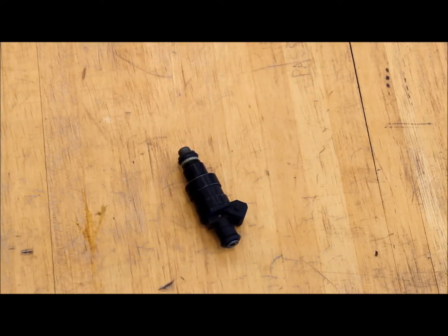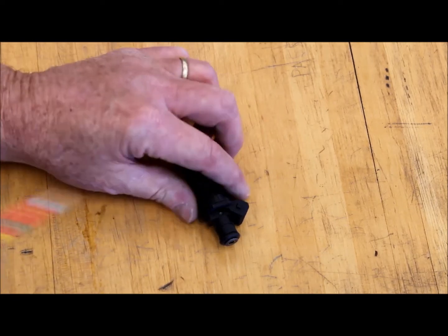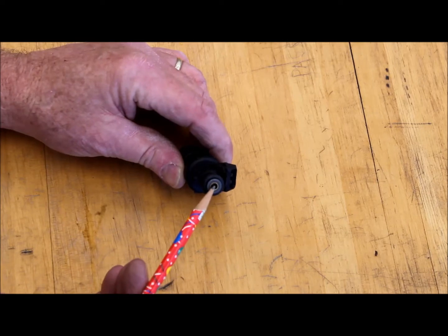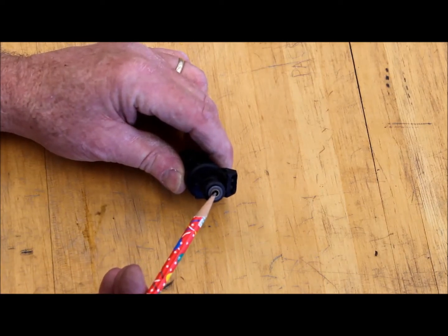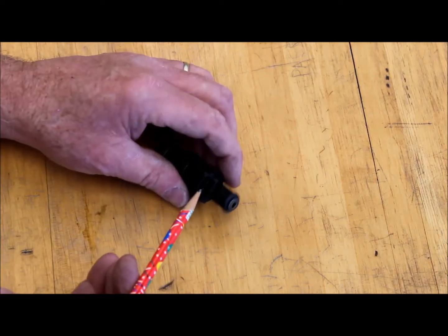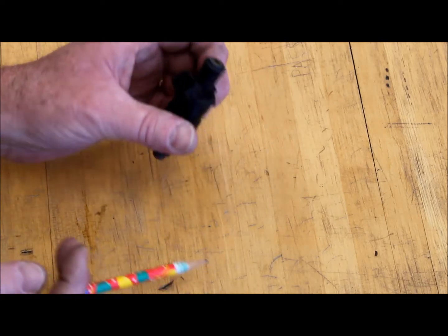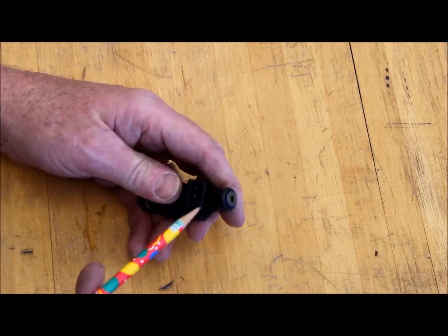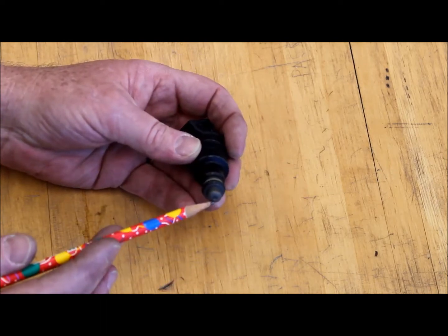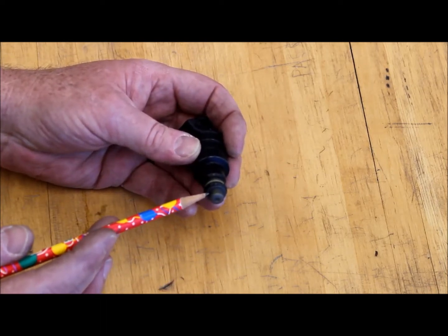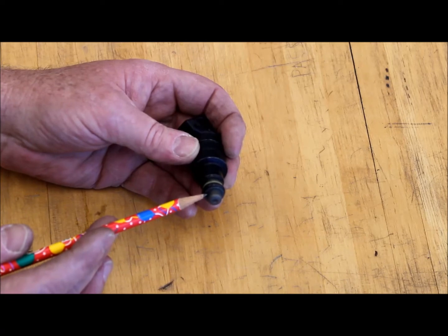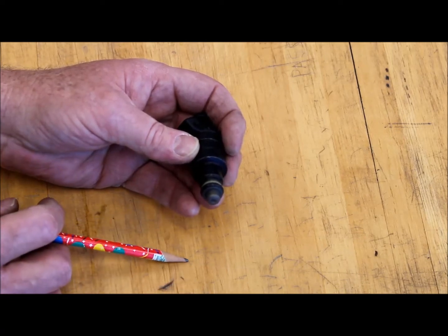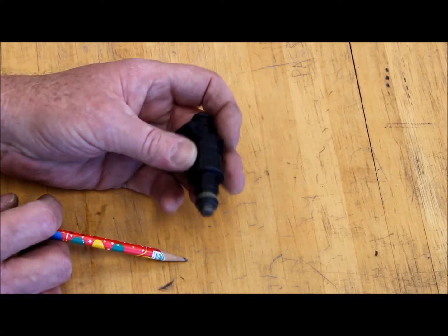So here's one example of a liquid control solenoid. This is a typical fuel injector, and if we look at it, we have the inlet where pressurized fuel comes in from the fuel pump. The electrical connector here, a little difficult to see, I suppose, 2 pins there. The outlet here that's directed either into the combustion chamber on direct inject or into the intake manifold on a port fuel injection system.